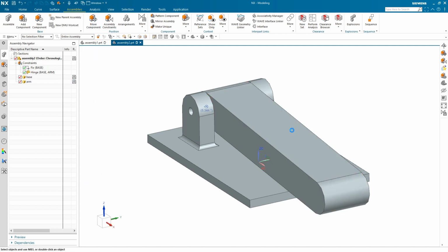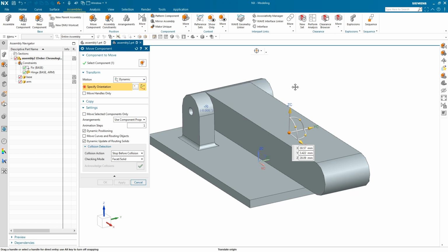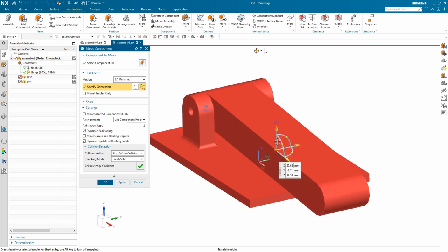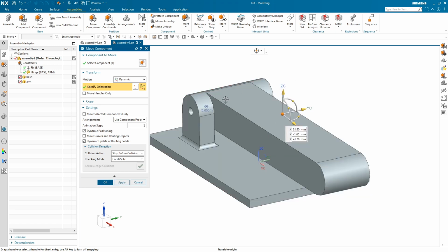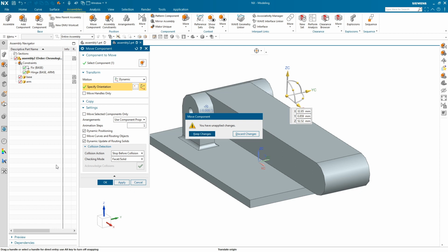Now when I move this component, you'll see that it locks out at 0 degrees. Oh, it's because I had the vectors flipped for the negatives. So above, technically up here is -90, and down here is +90. So it's only going to let me go between these two. Let me go ahead and change that real quick.